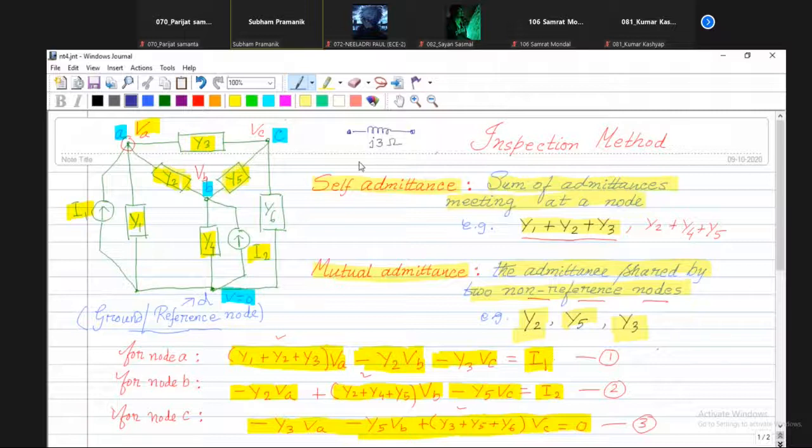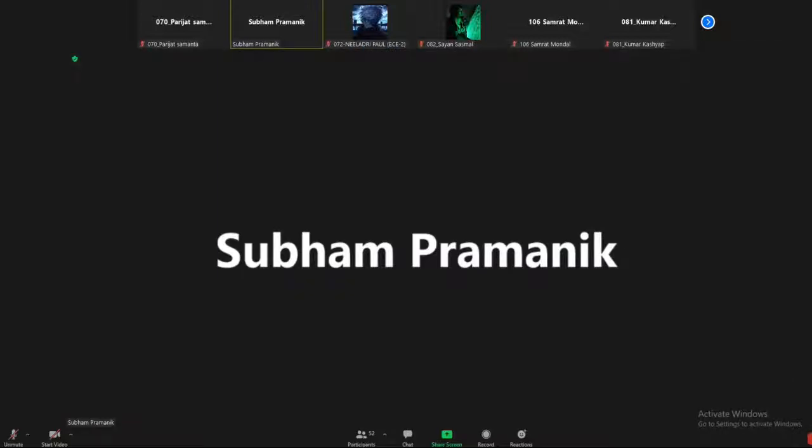What will be the mutual admittance term, can you tell me? 1 by J3. Yes. Remember, it is the admittance shared by two non-reference nodes. So if it is given in impedance form, then you have to take the reciprocal. Don't forget to do that. Anyway, let's go to that PPT presentation again.